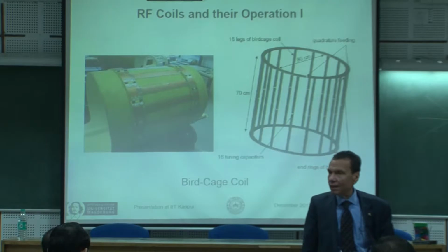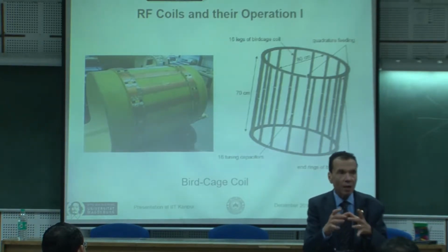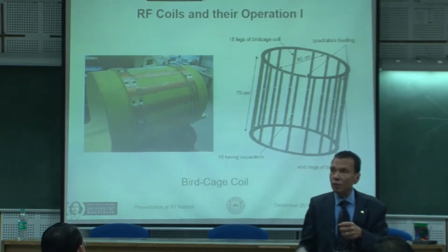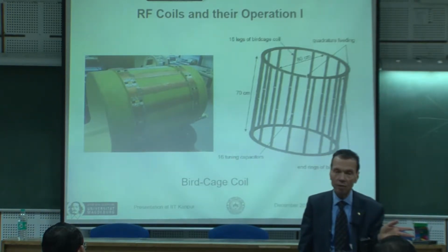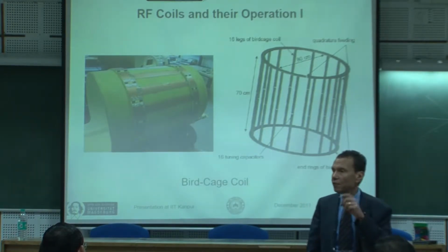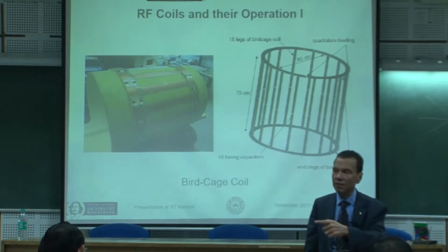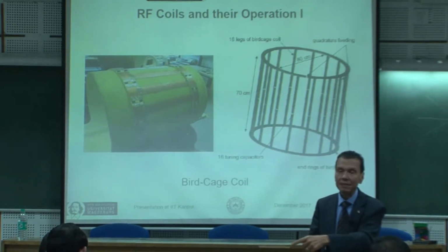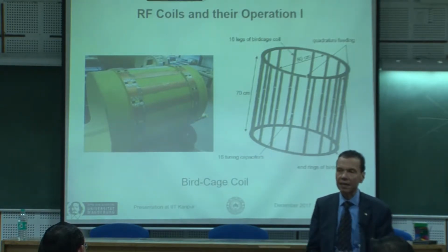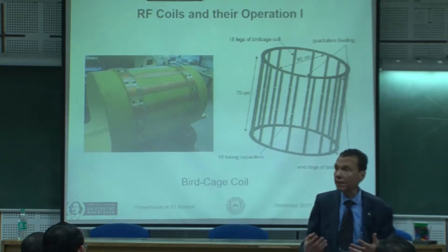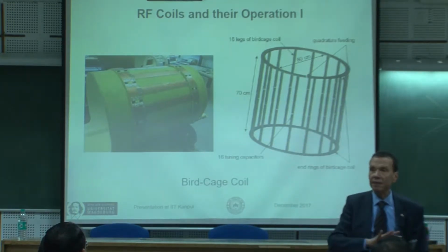Again, what is middle? It is some sort of approximation in terms of the frequencies. So you have an area in the middle where the field is really circularly polarized. Or if you have, say, 8 rods, and you feed with 0, 45, 90, and so on. This is one mode. There is another scenario in which you feed with multiples of these angles. In other words, if you have 0, 45 degrees spatial, you feed with 0, 90, which is double, or with 0, 135, which is 3 times. Some equations will show you that all these scenarios are possible for producing a circularly polarized field in the middle, because if you consider the whole area, you will never have it exactly circularly polarized.